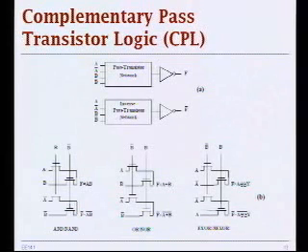Instead of having, I don't know, hundreds of cells, they have a library with just 4 cells made up of pass transistors, and they can synthesize pretty much any logic. So one advantage is I can have very, very regular structures, and I just change the inputs. I can change the functionality of the circuit. Any questions on this?